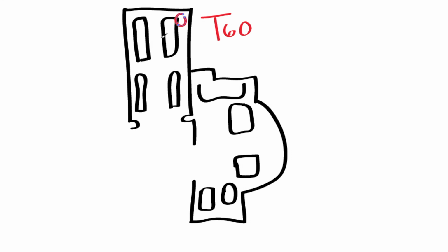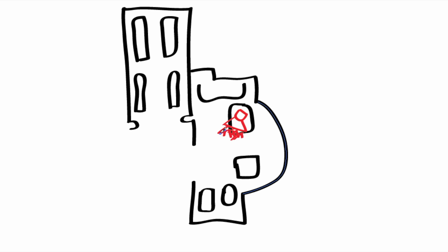We measured T60 in both the dining area and the bar area. The circles are the speakers, and we measured at the 6 locations where the X's are. We also took SPL measurements. We placed the speaker at the table where the noise is a problem, and we measured at various locations in both the bar area and the dining area.